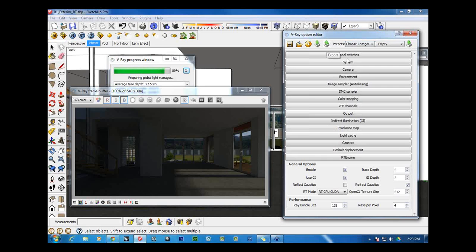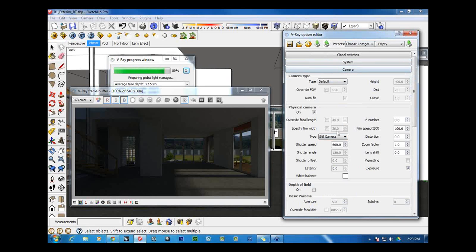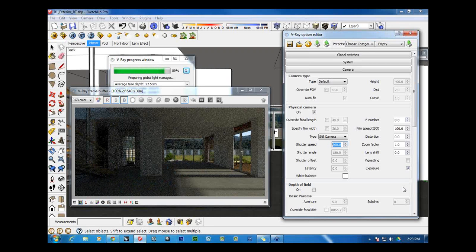When you export, let's say that you change the camera exposure here to 200, to 300, right? You change the exposure of the camera. If you export those settings, V-Ray will compare the change that you made with the default setting, and the values that are different from the default setting, we are going to get those values and create a VSUP only with those values.